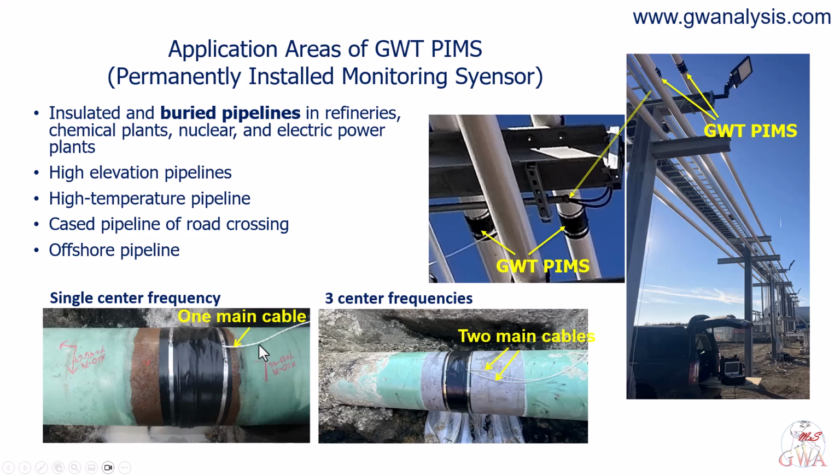Each center frequency has its own wavelength, and the wavelength decides which size of defect the wave interacts with strongly. A low frequency has a long wavelength and responds to large general wall loss. A high frequency has a short wavelength and responds to small pits. It also interacts differently with every feature and clamp on the line. That is the subject of several later modules, and it is one of the things I most want you to take from this training.